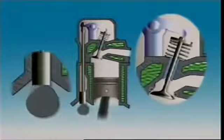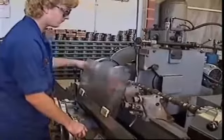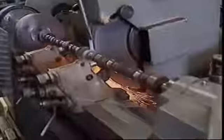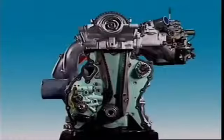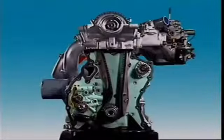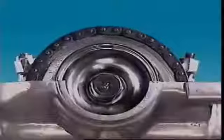On engines without valve lash adjusters, a quietening ramp is built into the shape of the cam. This makes for quieter operation during the opening of the valve. The shape of the nose determines how long it stays open. The camshaft must always be synchronized to run in time with the crankshaft. This can be done by gears, chains, or toothed timing belts.